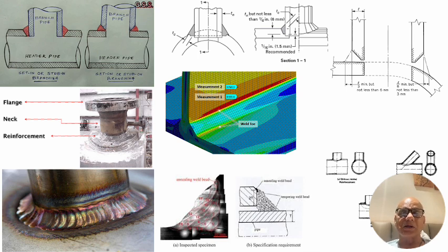So this weld, the last weld, is the most critical weld, which has to be deposited as shown here, and we have to take utmost care in this last run so that we don't land up with any defect, porosity, cracks, undercuts, or linear indications in any of our DP or X-ray.